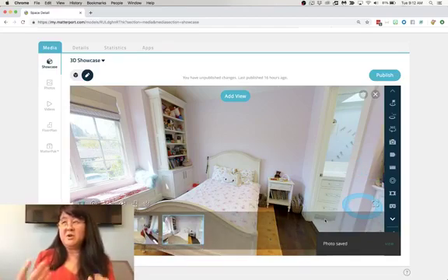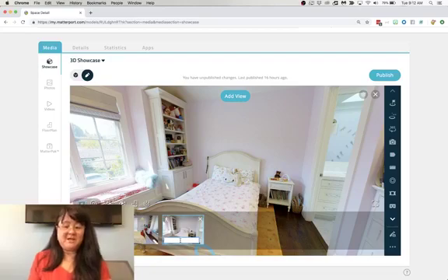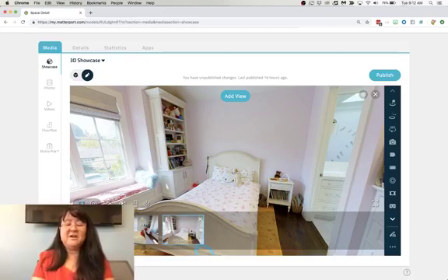So it's a little bit more work. You have to go between snapshots and highlight reel, but this is supposed to be more intuitively obvious, and I think you'll like it a lot more once you get used to it. The caveat here is to remember that if you want to add a caption to one of the snapshots in the highlight reel, you either have to hit the Tab key or the Enter key after you finish typing in the label, otherwise it won't be saved. This is a known issue that we are currently working on fixing, but for now, remember, for example, if I want to call this Kids Bedroom, I have to hit Enter in order for it to save.